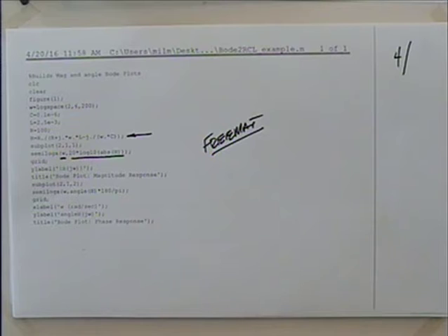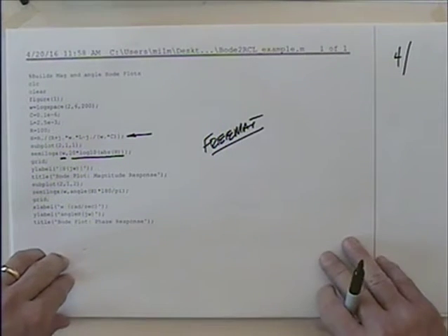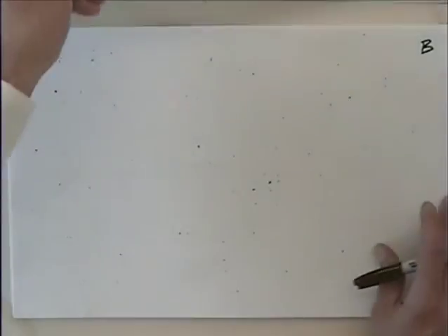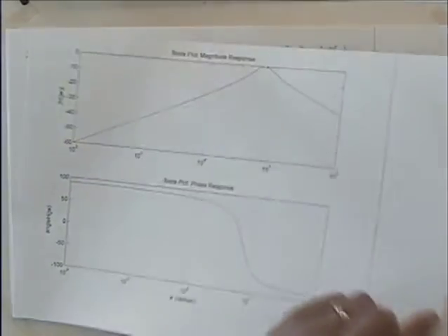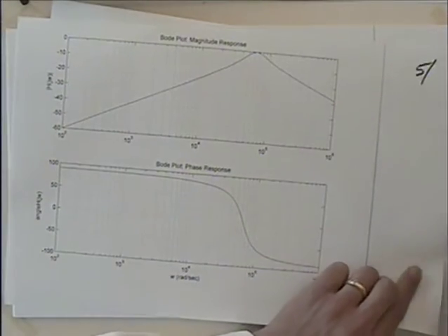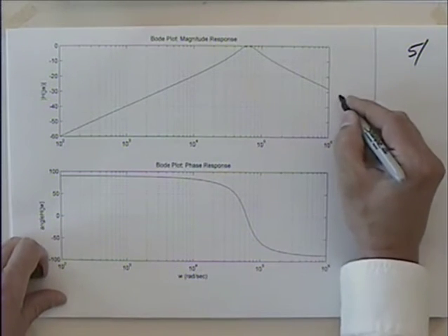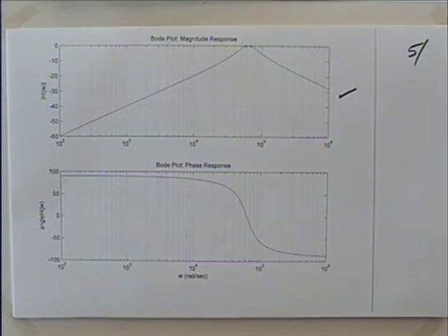These are things that this would have been a pretty decent final question in, what, GE 102. Just using a semi-log plot. We're using a semi-log plot. And when you get through that, you should come up with something like this. And we didn't talk too much about the phase angle, but the magnitude looks a little like what we've seen in the past. You could do that pretty easily with a straight line approximation.